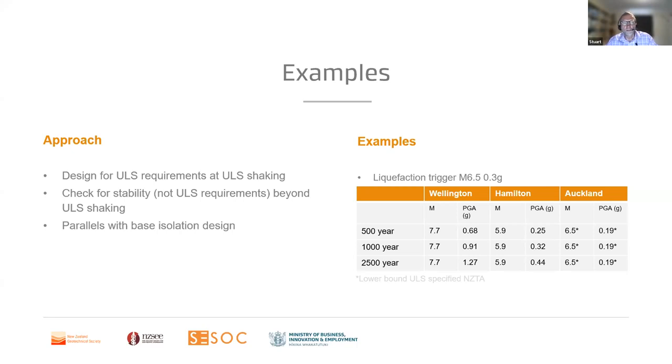Now, this sort of approach parallels what is done in base isolation design. So in base isolation design, designers need to think beyond ULS. They need to be thinking about the tolerance to displacement of the base isolators and the width of the rattle space. So the ideas that have been used there in base isolation are similar to what I'm about to present for these geotechnical considerations.